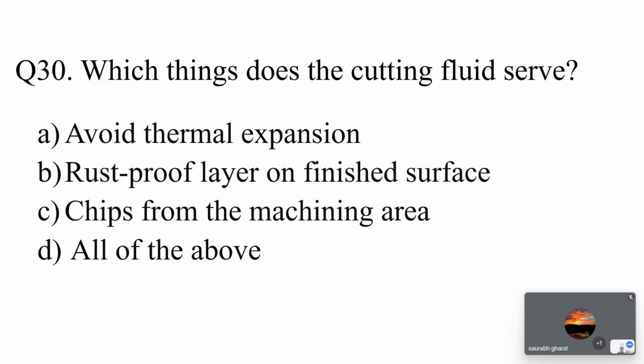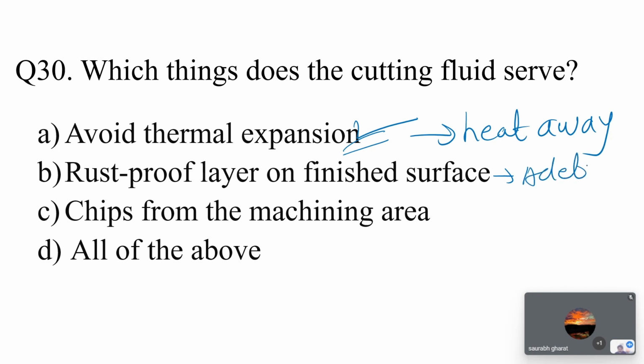So again, what does the cutting fluid serve? Avoid thermal expansion. Yes, it takes the heat away, so when you take the heat away, thermal expansion will be okay. It forms a layer on the finished surface because we are adding some additives, which correct the friction. It also takes chips away from the machining area due to high speed.